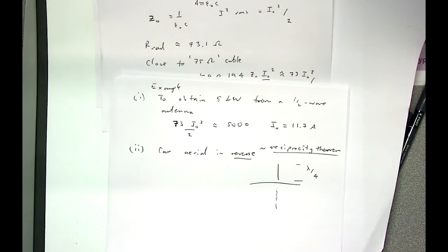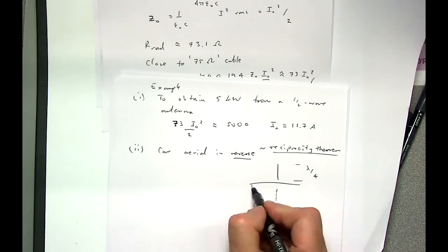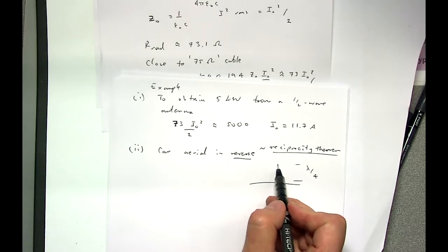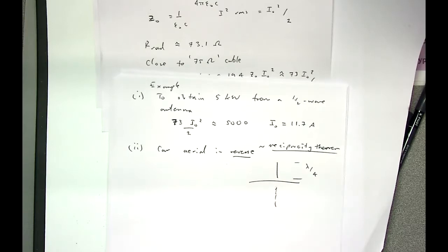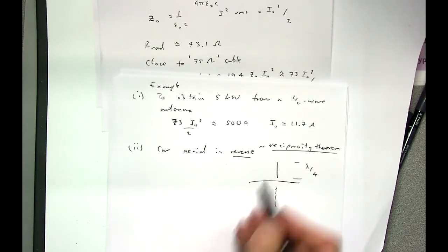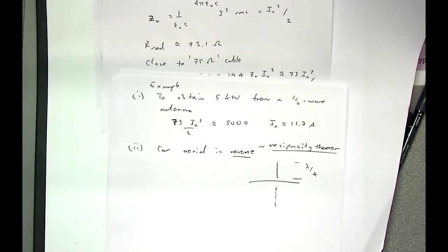Right? Okay, so this is a mirror signal. So I can use the overall circuits between this antenna and the roof of the car, and the physical length of the antenna is now about lambda by 4, not lambda by 2. Okay? So that's why the Winter Hill transmitter is lambda by 4 in length, because it's using the Earth as a whole as the ground plane. Okay, so it's like the car but bigger.